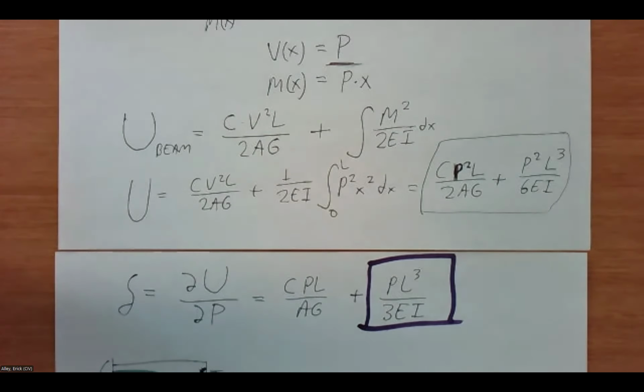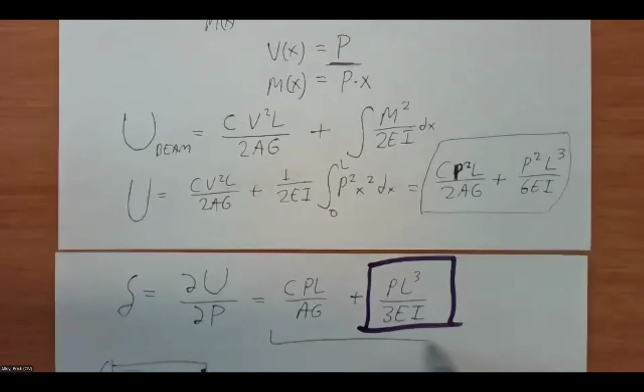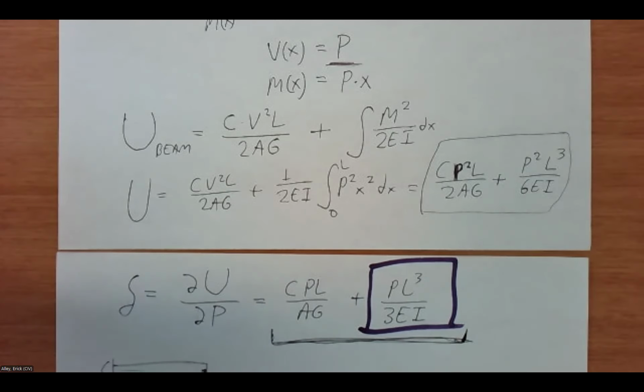All right, let's take a look. Throw a few numbers in there just to see what it looks like. Yeah, I got a question. So would you say that, in a sense, this is almost more accurate because you've got the extra factor in there? Yeah, this will add a degree of accuracy because it accounts for the movement of this beam, not just from the bending, the M of x, but also from pushing down with a shearing force.